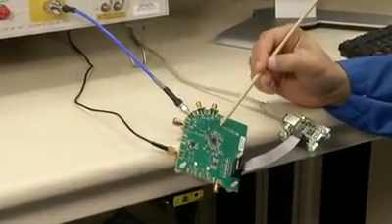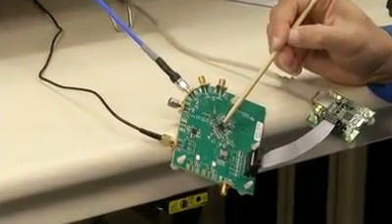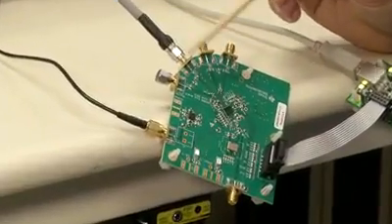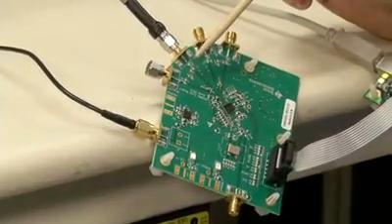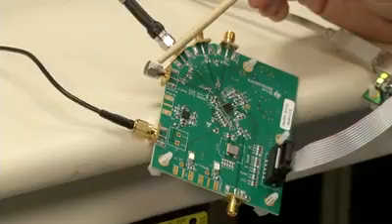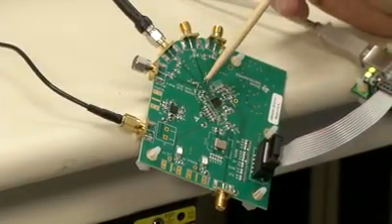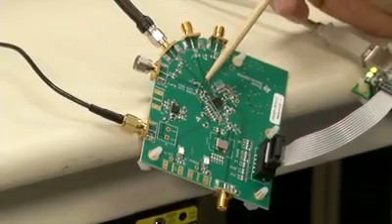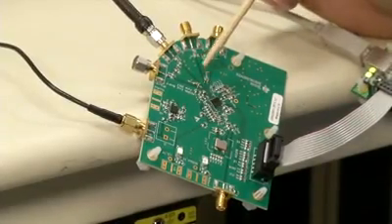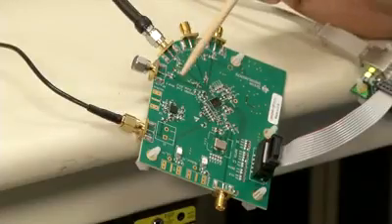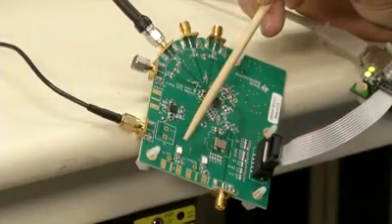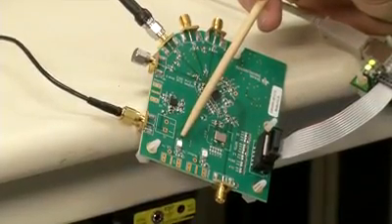Here on the evaluation board, we have the LMX2581 synthesizer. We have an output connected to my phase noise analyzer. We also have the unused side of this differential output terminated with a 50 ohm termination. This particular output has an inductor as a pull-up, which allows the high output power. Also on the evaluation board, we have an LED to indicate the device is locked.